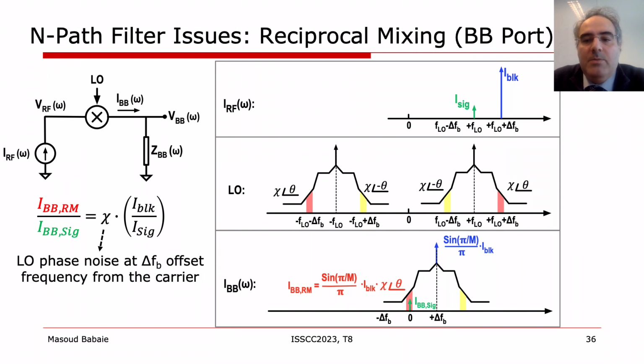The power consumption of the frequency dividers and buffers for non-overlapping clock generation is mainly determined based on the maximum possible SNR degradation due to the reciprocal mixing. Note that the frequency divider output noise can be largely removed by resampling its outputs with the master clock.